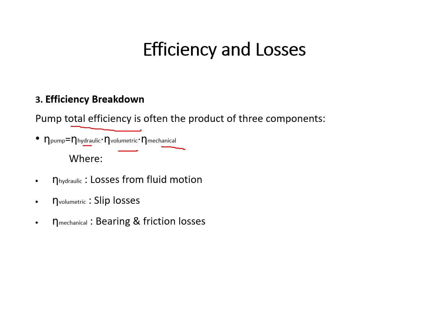How can we reduce mechanical losses? Most important is to use proper alignment and good lubrication to prevent losses of bearing friction. So, in general, the system should match the pump to avoid throttling and oversizing the pump.